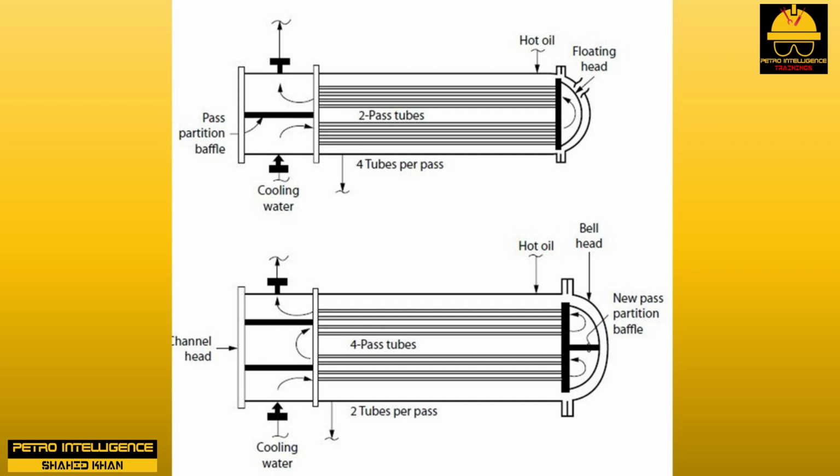If the water flow is restricted by increasing the number of tube side passes, then both total water flow and the tube side velocity will decrease. When the plant changed from 2-pass to 4-pass, the water flow decreased from 1 million pounds per hour to 350,000 pounds per hour. The method of calculation to derive the lower flow is somewhat complex. The calculations take into account that the water has to flow twice as far through the tube bundle, and that there are only half the number of tubes available per pass, but that the water pressure drop must remain constant.